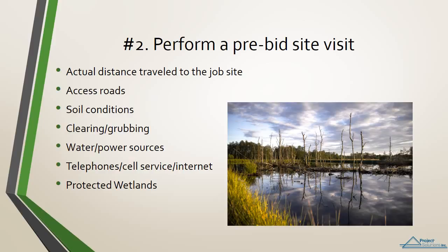Actual distance traveled from the office to the job site, and will per diem or lodging need to be provided to on-site workers? Is there adequate access to the job site, or will access roads need to be developed? From a visual inspection, what are the soil conditions? To what extent are the clearing and grubbing requirements? Is the site mostly grass and weeds, or are there a considerable number of trees? And if so, what is the average diameter of the trees?